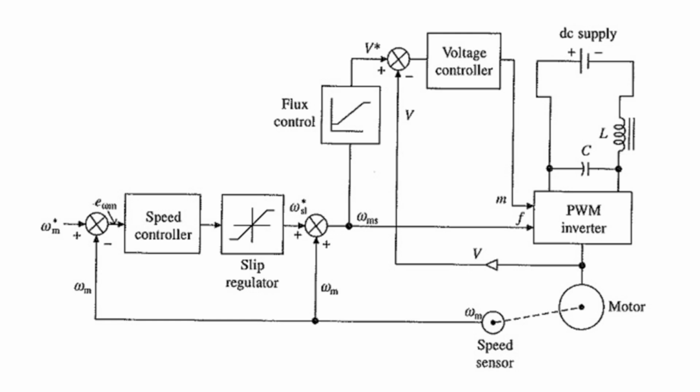Generally, below base speed, we have constant flux operation. Above base speed, constant terminal voltage operation. Generally we choose constant flux operation below base speed, up to base speed, and above base speed, constant terminal voltage operation. That's why we are choosing two parameters.